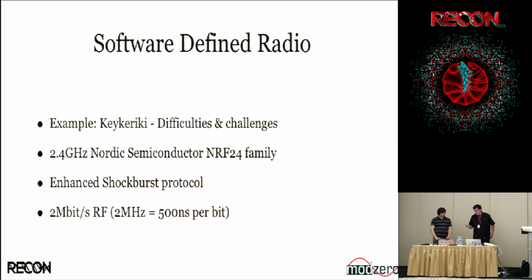So the problem is that, in theory, you have like 50 clock cycles with a microcontroller running at 100 megahertz, but in practice, minus all the overhead for interrupt routines, you have like 30 clock cycles for what can be done in an FPGA within one single clock cycle.